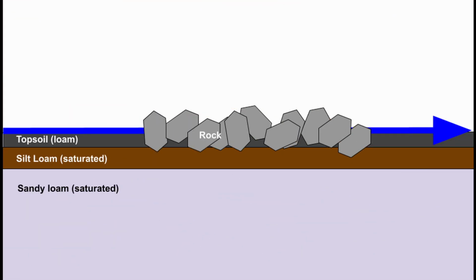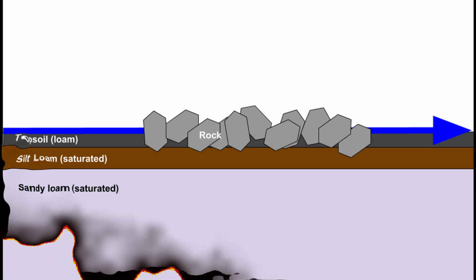The rock used in this spillway is also bad news. The person building this wetland tried to save money by spreading a thin layer of rock in the spillway. The rock they placed is barely pushed into the ground. See how the rock sticks up high from the surface? Water flowing in the spillway will be deflected when it goes around the rocks that are sticking up on the surface, and there will be erosion.